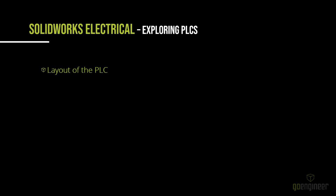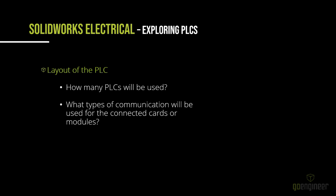When I'm talking about the layout of the PLC, what I need to think about is how many PLCs we are going to use. Do I have just one main PLC? Do I have things like connected cards or modules, meaning flex I/O? Is there a rack? Am I using cards? Is there a power supply that should go on those cards? Is there remote I/O? These are the types of things that you are looking at when you are looking for the PLC layout.